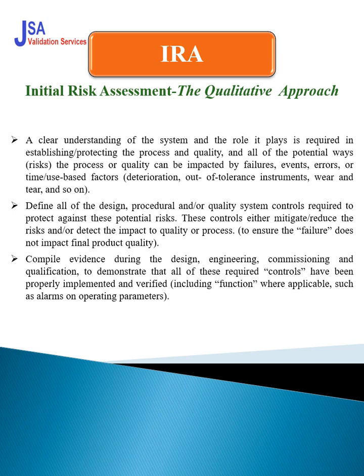Suppose there is a risk with the compressed air system, high dew point. The dew point is out of limit, like you have the limit of minus 40 degrees Celsius, then it goes to minus 30, minus 20. So your air dryer may have tripped. Due to some reason the air dryer is tripped and your dew point is going to the higher side. So what is your control? This is the risk to the process. The water is going inside the pipelines and that will contaminate the product. So that is the risk. Now what is your control?